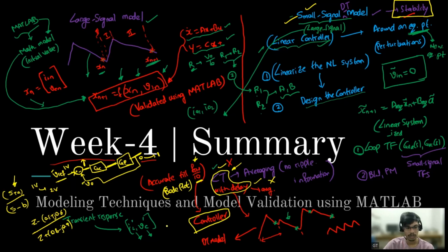One basic question: what is the use of state space actually? State space predicts the dynamics of the converter, or whatever system. Using this, we can predict the dynamics of the system. It is more like we are modeling the system. For example, I have given a buck converter. Inductor current and capacitor voltage are states, and we are just getting the relation.